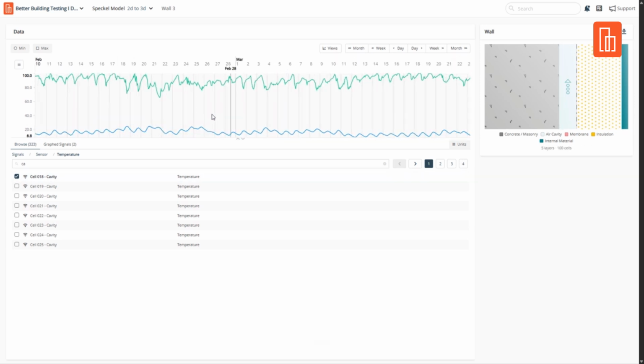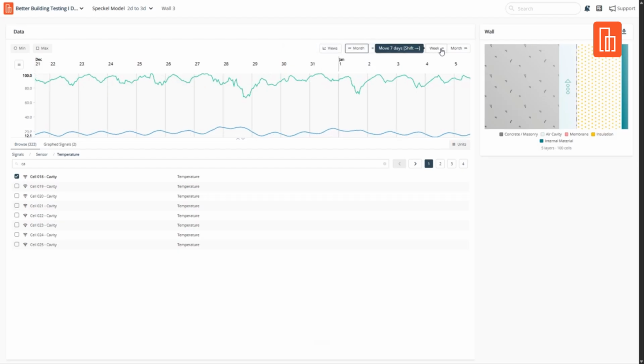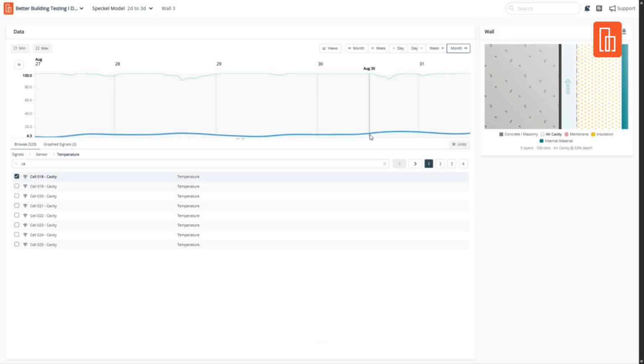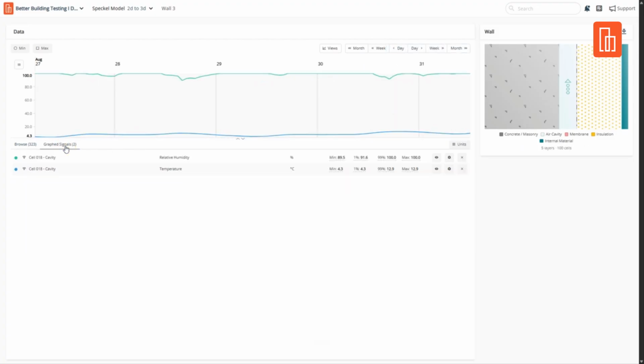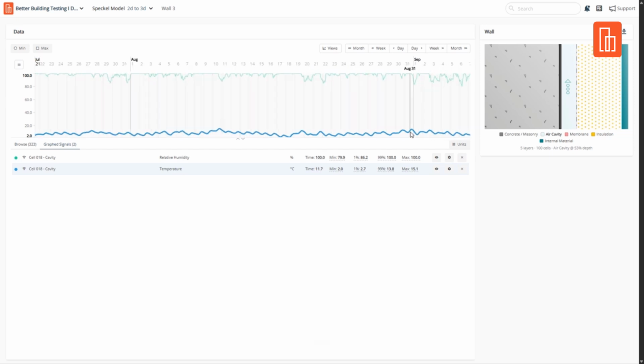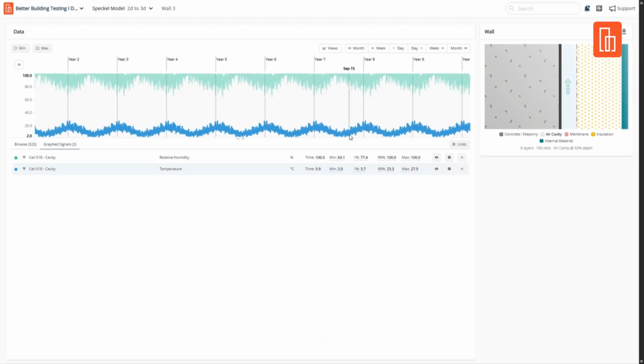It might take a bit of inference here. We can flick through the months should we want. And yeah, I'm just getting to the cold point here, but it actually looks like interestingly that the cavity itself, and if we go to graph signals here, I can just nominate along there, but the cavity itself maintains quite stable yet very, very low temperatures during those winter months, and thus increasing the risk of saturation on the back of the actual panel itself.